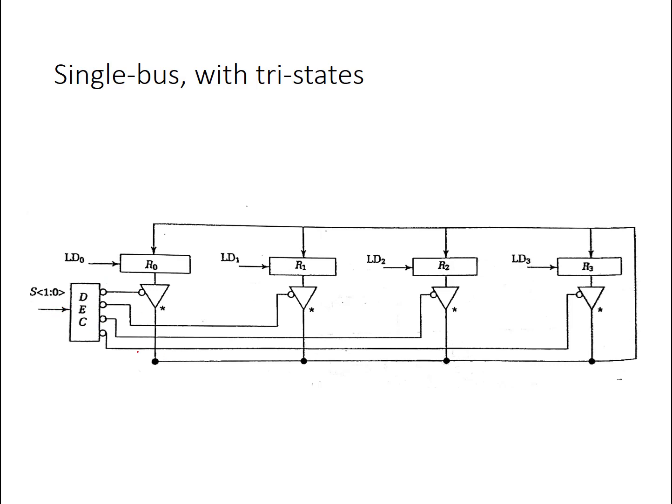And in this case, this will guarantee that we have only one of these tri-state devices driving the bus at a given time. This is an important aspect to make sure that you design correctly when you have buses and using tri-state devices, that you have only one device driving the bus or connected to the bus at a given time. Otherwise, this is when you'll likely start to see things smoking or damaging your internal circuits with too much current flowing.